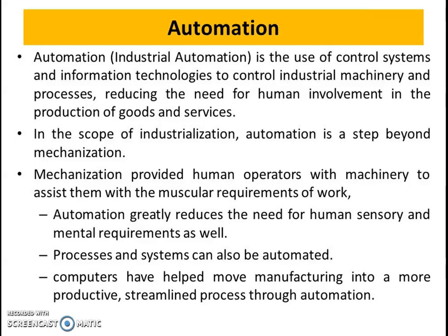the chuck key. With the help of the chuck key, you have to open the chuck and insert the rod. Again, you have to make sure that the rod is at the center, and you have to assess the length of the rod, and ensure whether the tailstock is necessary or not. Once everything is fixed, you have to make sure what RPM you have to set, and based upon the RPM, the tool has to be fed, okay? And all these things have to be done manually, right? And now, if you see CNC machines, flexible manufacturing system, you call it FMS, right?